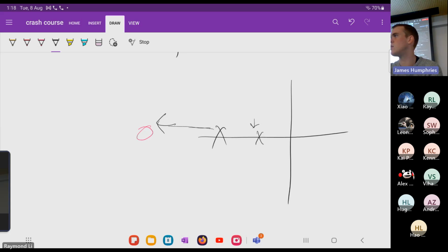So let's just say that. Well, that's why we add the zeros, because the whole point of the zeros is that it attracts the poles. If there are no zeros, then the poles go at each other and then expand far away. Right, but they have to go somewhere. Can't they just stay on the real axis?